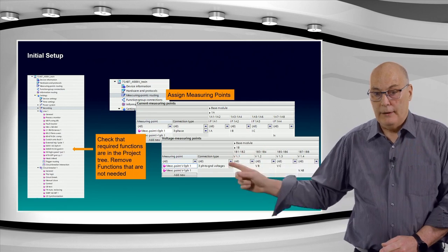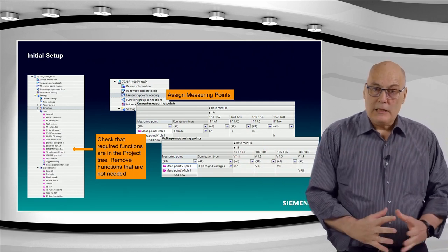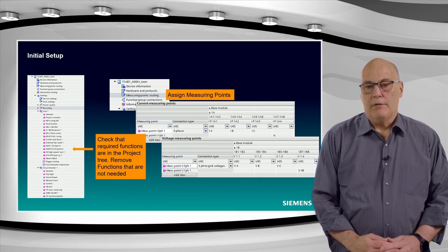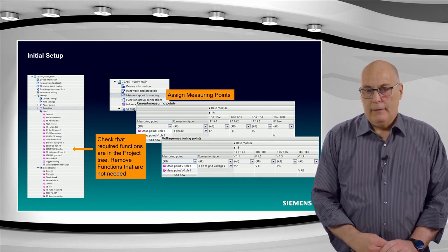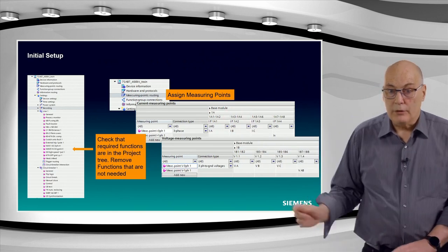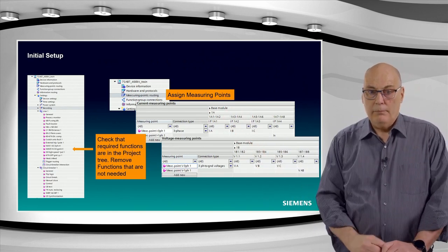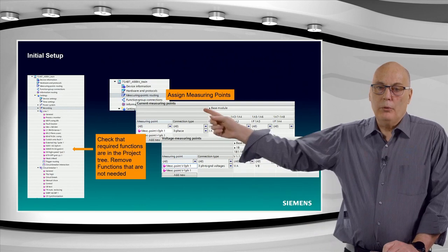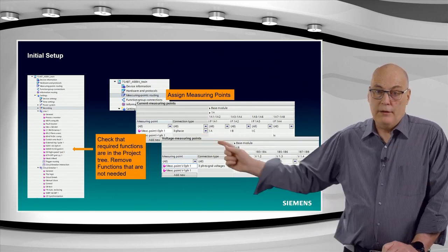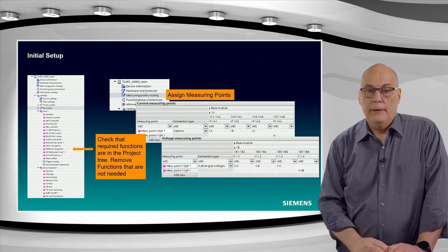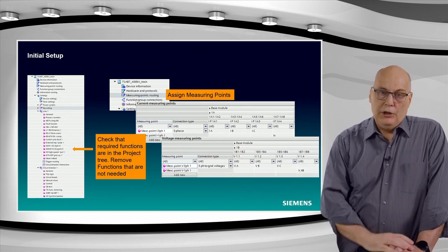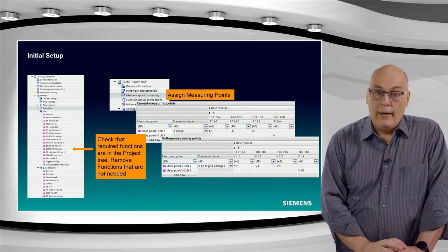The other thing we have to always see is the CT-VT connection, another key aspect for the relay. If you're going to apply that, you have to make sure that the CT and VT are connected to the function. That is done in the DIGSI configuration under the measurement point routing. You can see here, physically in the middle, that would be the current measuring point. So I have defined here 2 current measuring points. It's interesting, the one, a 3-phase current measuring point, is going to be the one connected to the protected line.